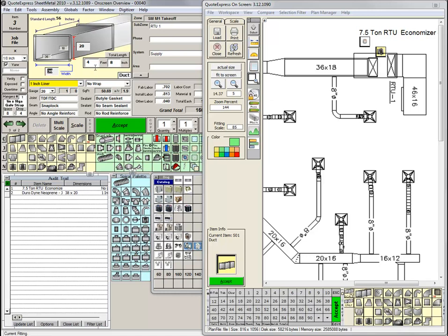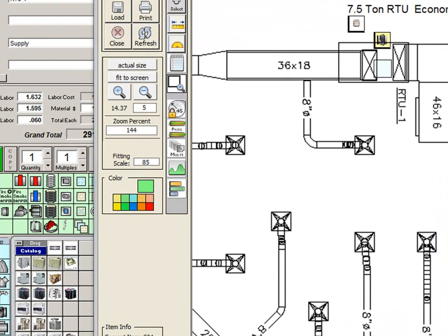The next step is to only put in the feet that I wish to use. Click into the feet box, go down to the number palette, and select how many feet you would wish to use. In this case, we'll use 6 feet. I'm then going to click on the blueprint where I would like this item to appear.